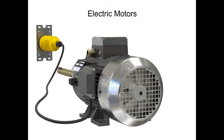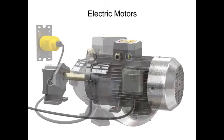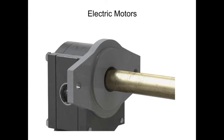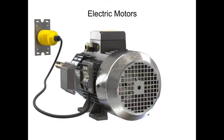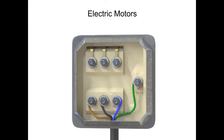Since these multi-directional motors are equally efficient in either direction, there's no standard direction of rotation. Therefore, when a three-phase motor is first connected, it may run in either direction, and technicians must be careful to install it properly. While the motor itself can run in either direction without harm, the components that the motor drives may be unidirectional. For instance, running a pump in the wrong direction may cause damage due to cavitation or expulsion of the shaft seal. If the motor's rotation is incorrect for the required application, it can be reversed by simply interchanging the connections to any two of the three power wires.